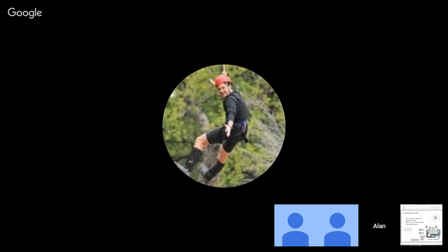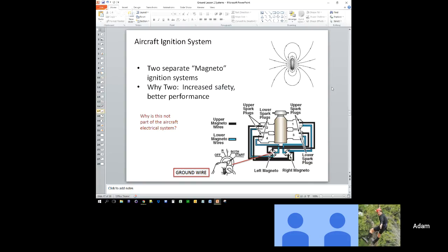So you remember the Luscombe at my cousin's place? That's how they were started. That's basically the mechanism by which the engine was starting. That's exactly right. She turned the prop through as many revolutions as she could physically turn it. What that did was rotate the shaft in the magneto, which created an electrical field momentarily across the spark plugs, and probably one or two cylinders fired, just enough to get the engine started. The starter actually works the same way. Instead of using the propeller, it's got a flywheel that actually turns the engine.